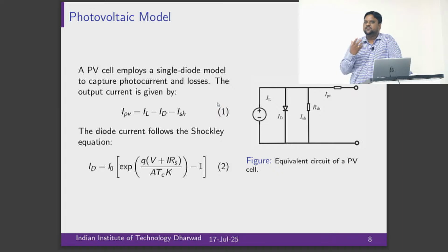So, basically solar cells absorb the radiation and convert it into electrical energy. That photocurrent IL I represent, and there is a parallel diode also. You know the current through the diode is not linear, right. That diode current expression is provided in equation number 2. It is basically an exponential function and depends on several factors, and there is a shunt resistance and a series resistance. Okay.